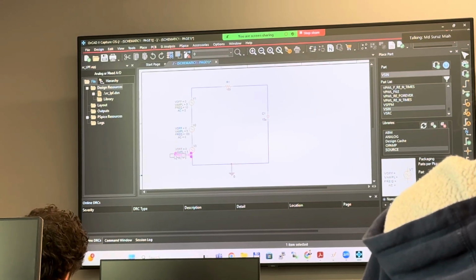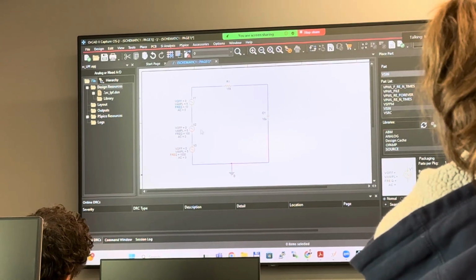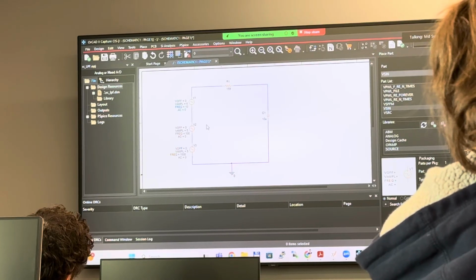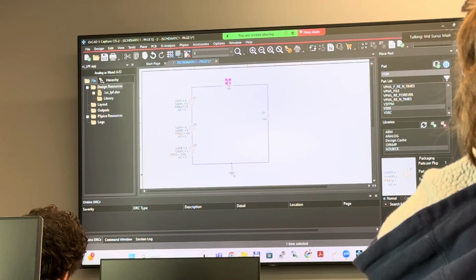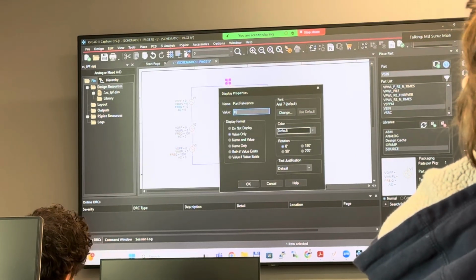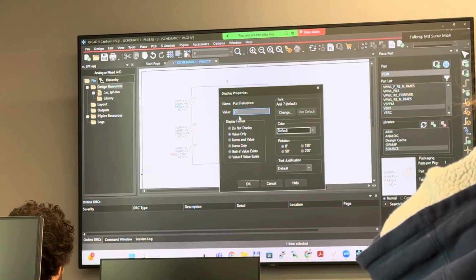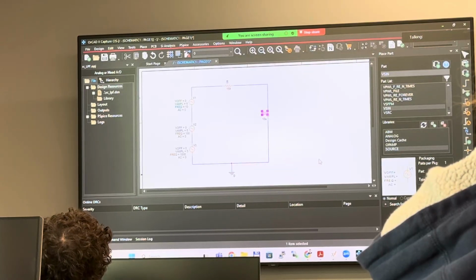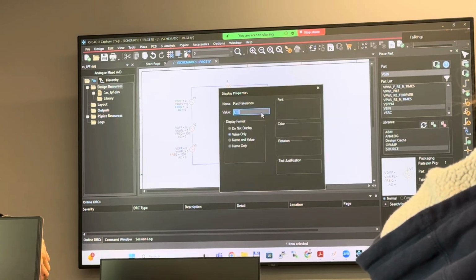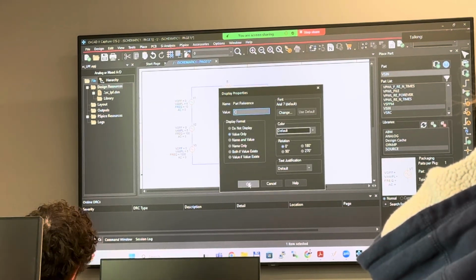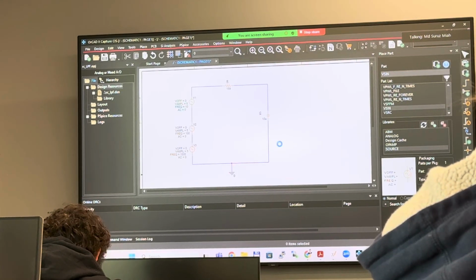You can select and move it to the left so that you can see. So we have 3 sinusoidal components. They are added together to make the input VI. And we have a capacitor here, we have a resistor. I'm going to rename it and call it simply R, and double click here and call it simply C. Okay. All right. Now save.